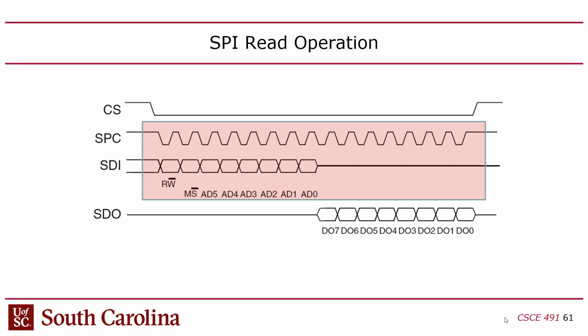Yeah, it's not a lot. A lot of these peripherals are pretty limited, they don't have that many addresses, although 64 still sounds small. But yeah, so then you put 6 bits of address, and you can think of this as your network header, your packet header. That's how I think of it.